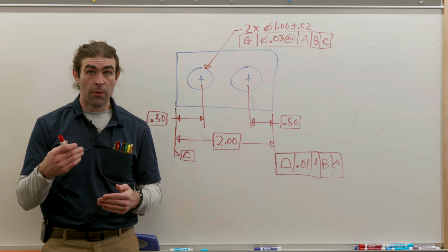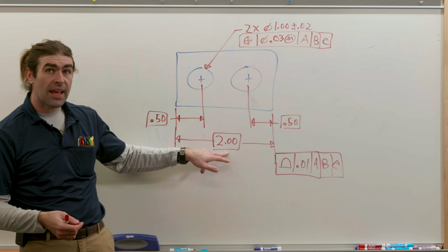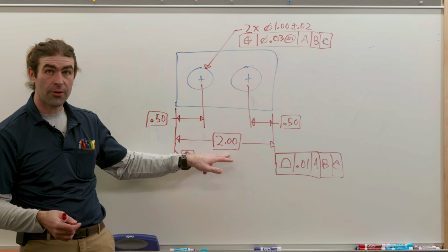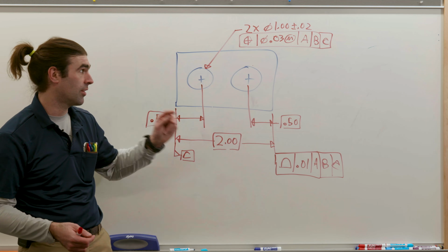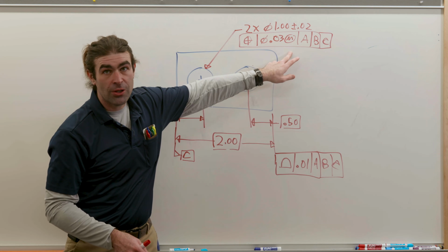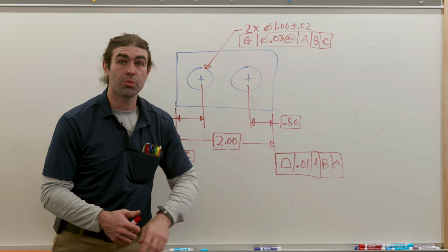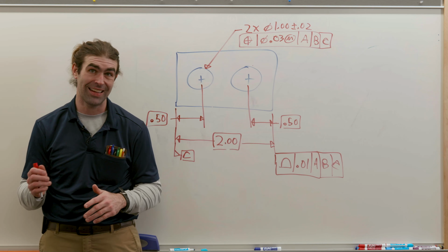Now, at inspection, you really shouldn't indicate the tolerance or the actual dimension for basic dimensions. Okay, so all of these dimensions here are associated with either this position or this profile. That's where the tolerance for the basic dimensions is.